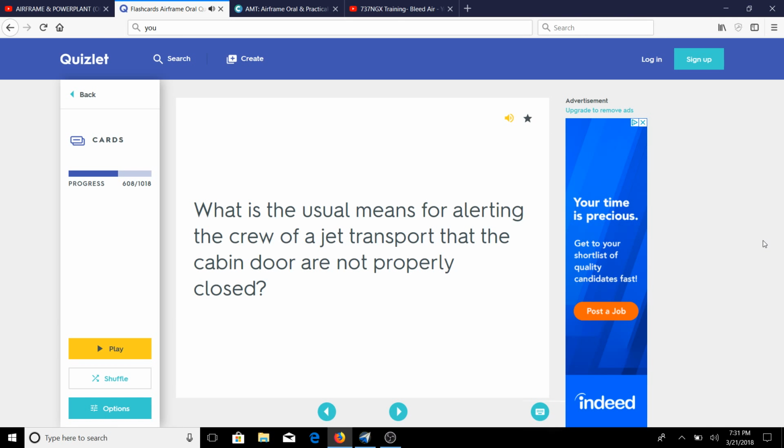What kind of device is normally used as a sensor to detect the condition of a retractable landing gear? A precision micro switch. What type of system is used to indicate the position of the wing flaps? Usually a resistance type remote indicating system such as the DC selsyn system. What information is shown by the wing flap position indicator? The number of degrees the flaps are lowered.